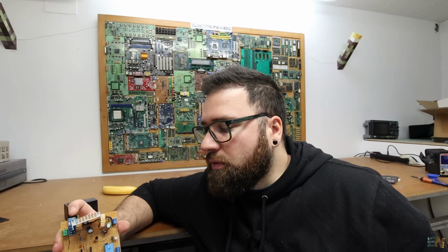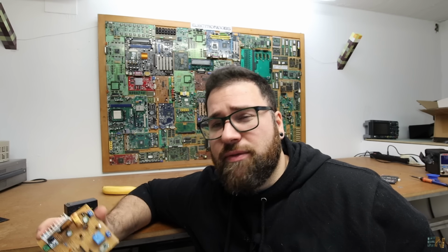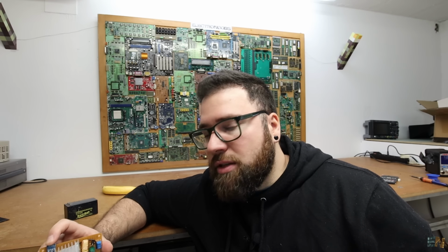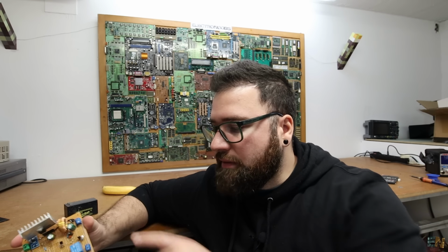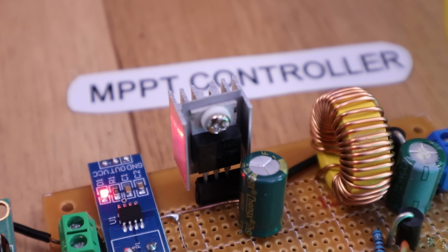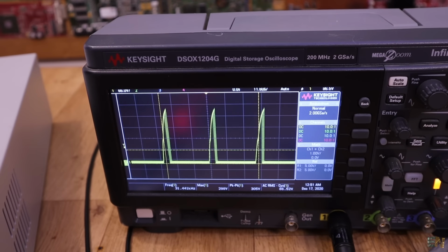And I'm thinking of using a different sensor, because this sensor is very good. It's based on Hall effect, so you are not interfering with the circuit. It is insulated from the circuit. But the problem with this one, since it's based on Hall effect and I have a buck converter here, is that this generates a lot of magnetic fields with the coil and everything, and sometimes we have some peaks of current which are not really there. So I'm not sure if that is the good way to do it.